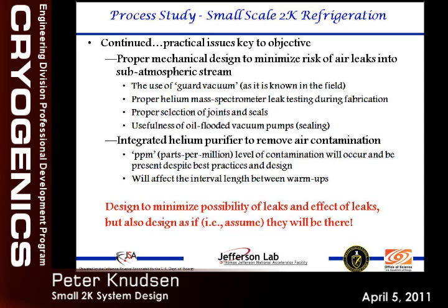Some other practical issues here are the mechanical design needs to be considered. We use something called guard vacuum, which probably a number of you are familiar with. It is basically an intercept at a lower pressure than the process pressure, that isolates between atmosphere and the process that's in between. That, in addition to good mass spectrometer testing to make sure you don't have leaks, is important. Also, very importantly, an integrated helium purifier.